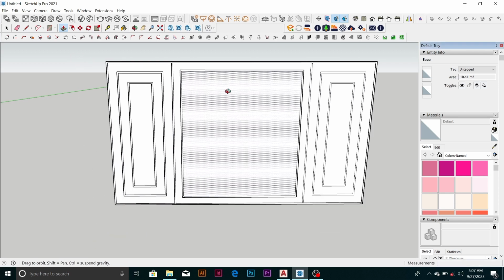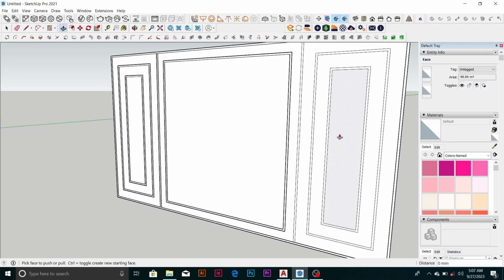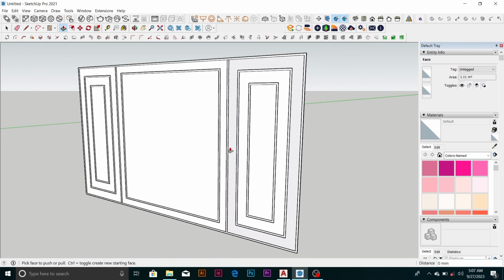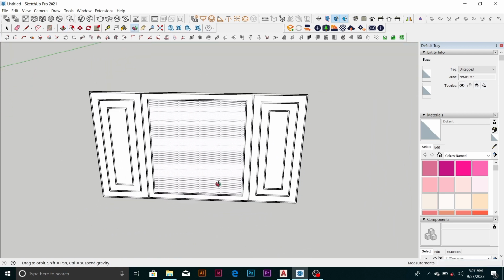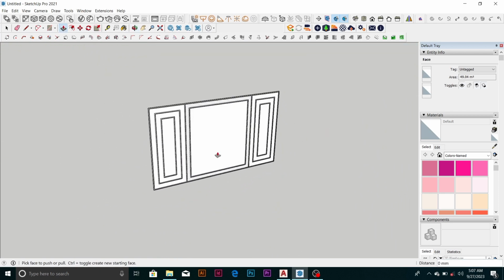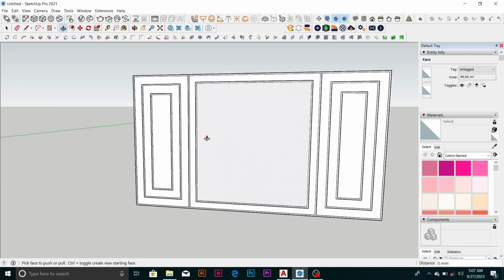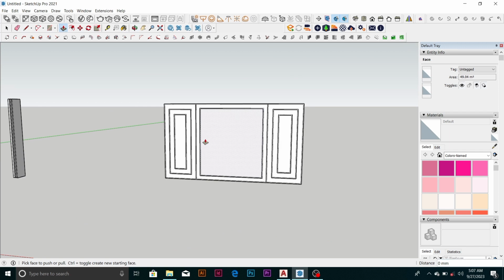You see, I'm just pressing the control. I've pressed the 30 before. Instead of continuing to press it again, just press it twice. You see the surface we are forming with the push pull tool now. So that is the decorative modeling I'm doing with the push pull tool. So that is the second practical scenario.